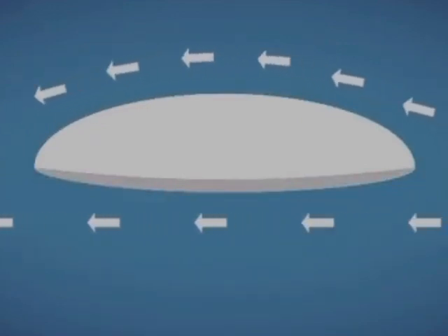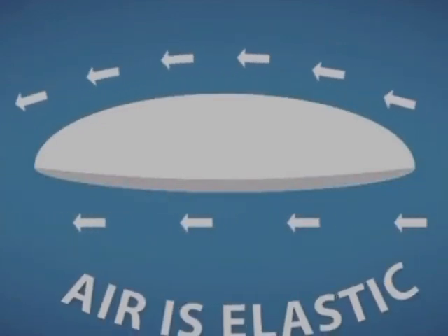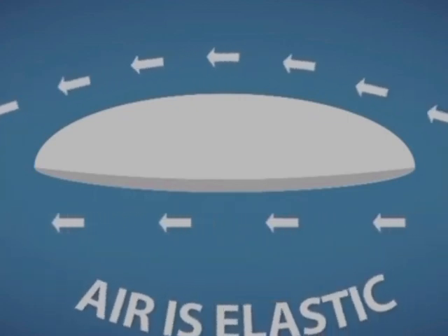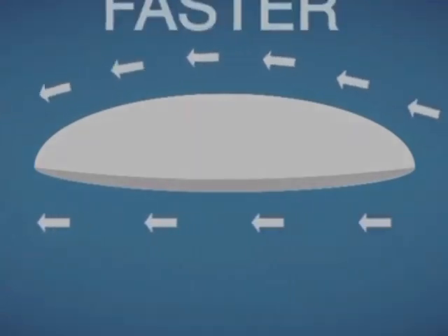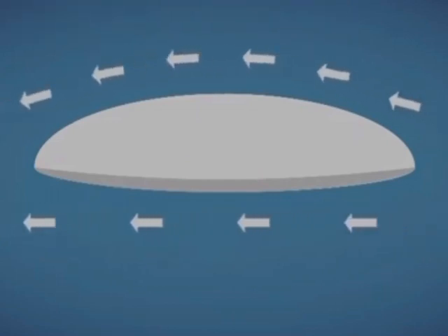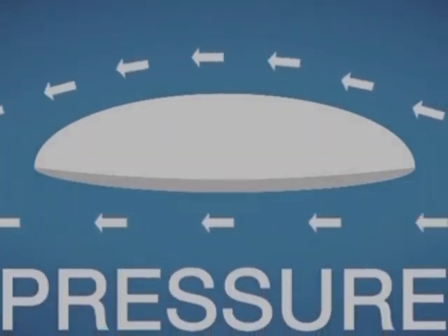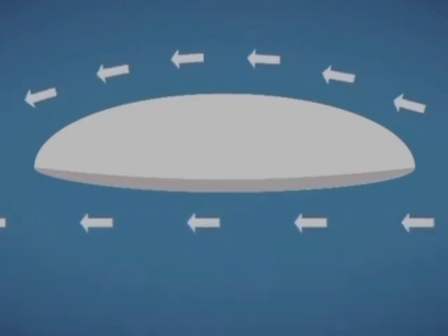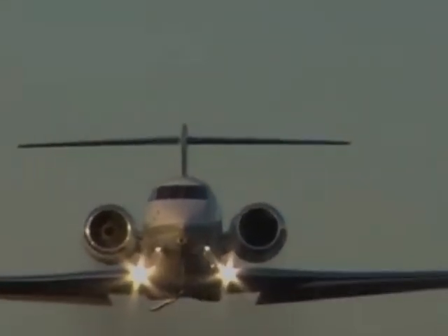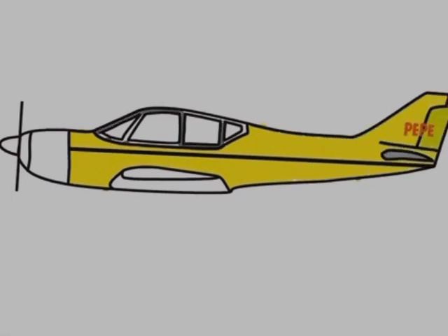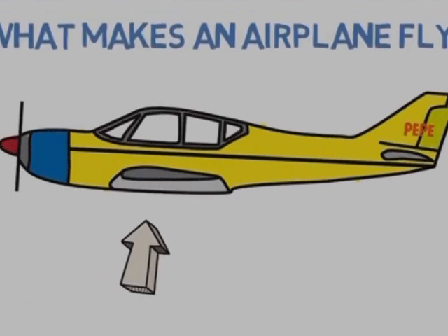The same principle applies to the wings of an aircraft. So in order to help the wing generate lift, we need the particles of the air flowing on the upper surface of the wing to flow with a higher speed, and the particles of the air which flow on the lower surface of the wing to flow with a lower speed.